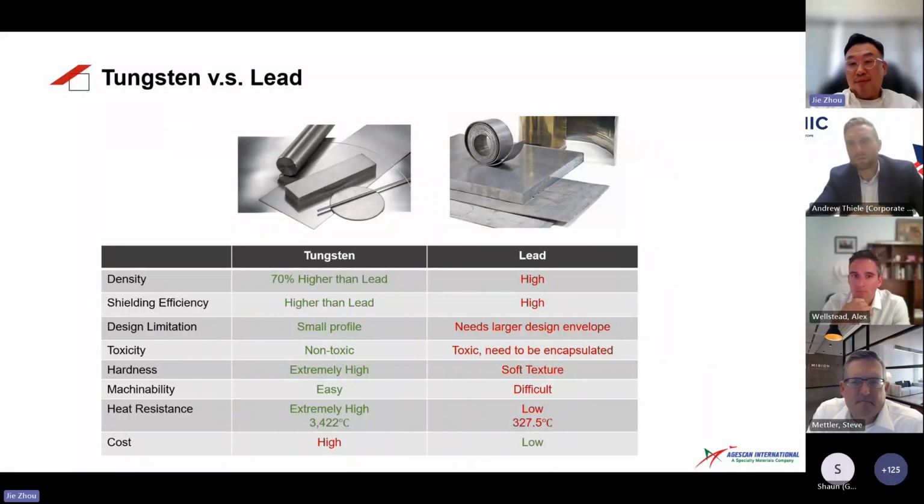Normally, tungsten alloy has an HRC value of 28 to 32 HRC. Tungsten can be tapped, drilled, and faced to have a complex structure, as we discussed earlier. On the other side, lead has a softer nature, and the pressure from the fixture and cutting tools on lead-based parts can cause the product to be out of specs.